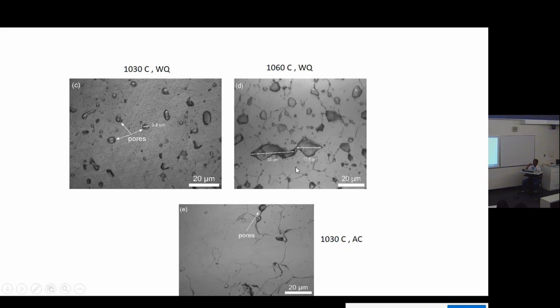We think that when we spray, one of the other things I forgot to mention is that with this cold spray method that is developed by P3D, they use simply compressed air to propel the powder, whereas all the others use either nitrogen or argon as the propellant. So we believe that because of that, the air trapped in between the powder is probably responsible for this flare up. That's what Tian says, and I believe that.